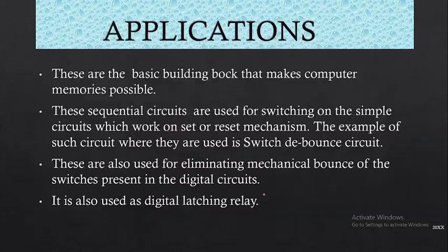Now let's move forward to see some applications of an SR flip-flop. These are the basic building blocks that make computer memories possible. Second, these sequential circuits are used for switching simple circuits which work on a set or reset mechanism. An example of such a circuit is the switch debounce circuit.